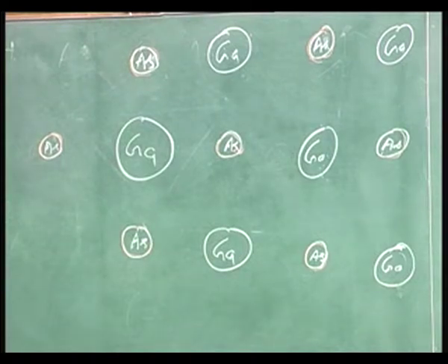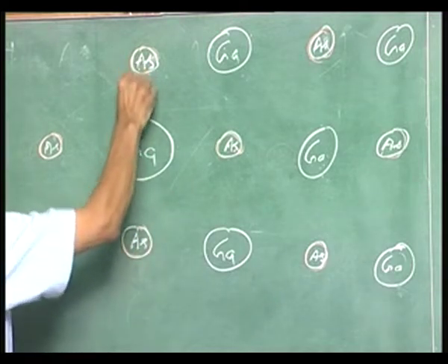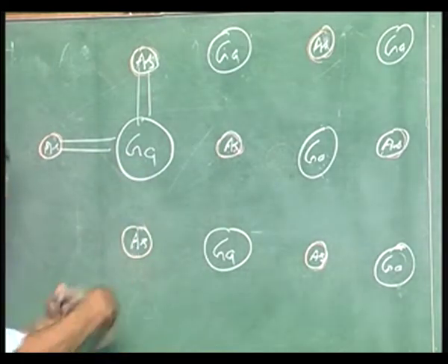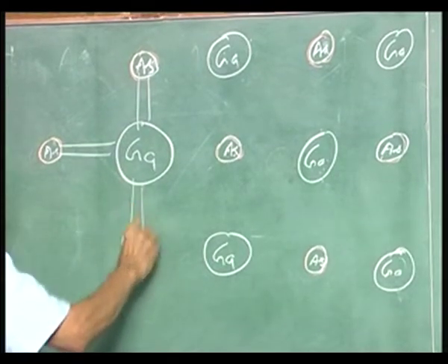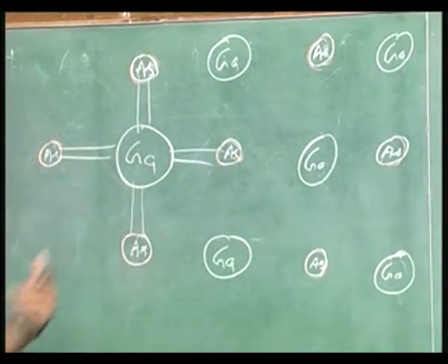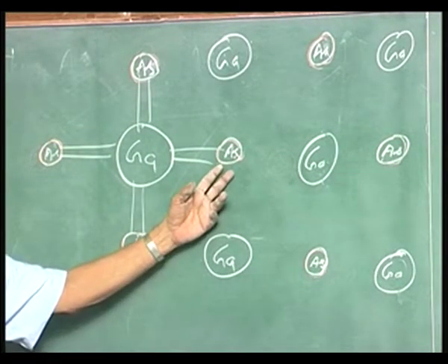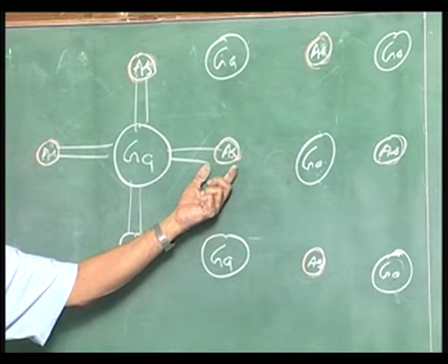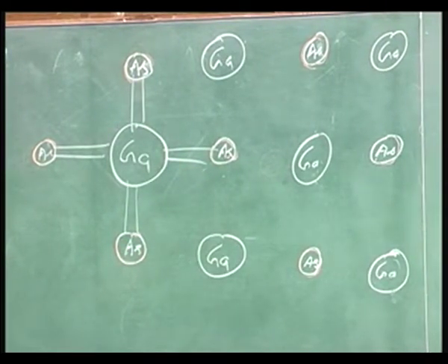Whereas in silicon, you draw the same structure with silicon everywhere. Now, you can see that bonds are like that, 2 you put to show that it is on an average 2. In silicon, you put 2 like that, total 8 electrons. And these are the electrons which you represent, which form the bond. Now, arsenic has 5, therefore, one of the electrons will be slightly displaced partially towards it. So, it will have a slight negative charge on arsenic and positive charge on gallium.